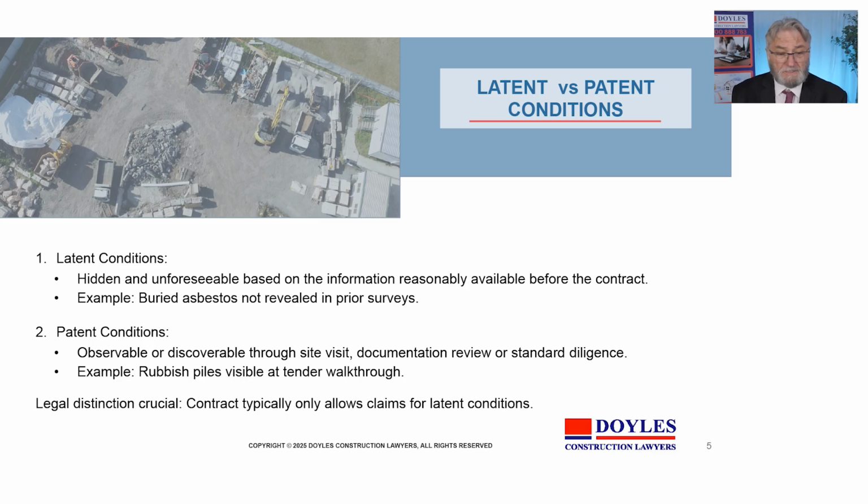Now, if we go on to discuss latent conditions, they're hidden and unforeseeable based on the information reasonably available before the contract started. Now, of course, the advice of the wise is to make more and more geotechnical inquiries, and that might remove the risk of, say, rock. But principals particularly don't want to invest further money in surveying something that's not usually there, so they often cut down on those surveys. And what you find in a general construction job, whether it's for a building or a road, you find bore logs at widely spaced intervals. And the usual gossip in the industry is the bad conditions are anywhere except on the bore logs.